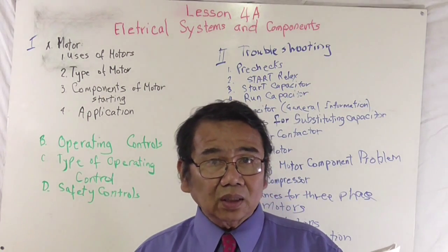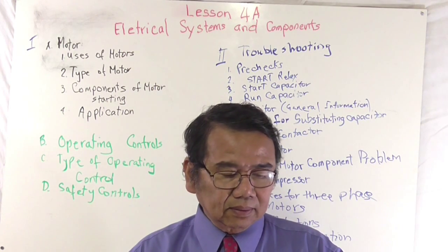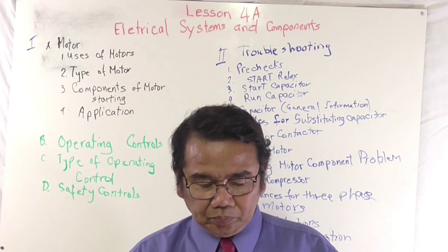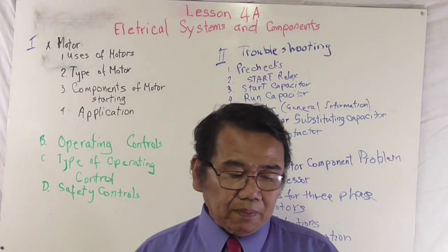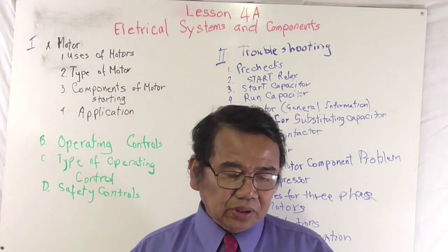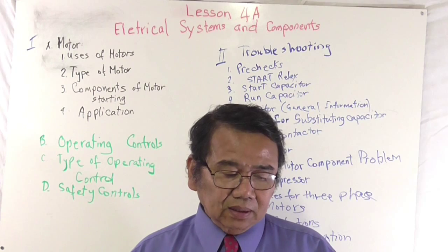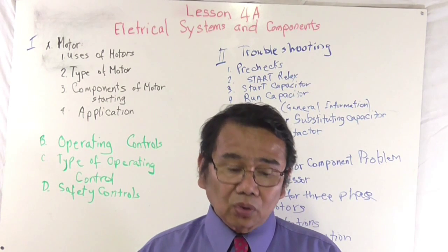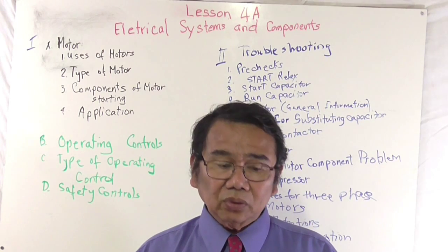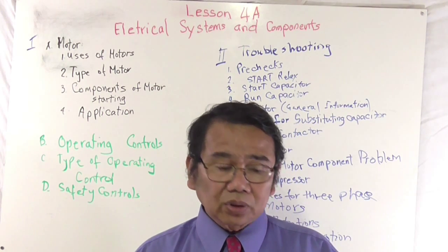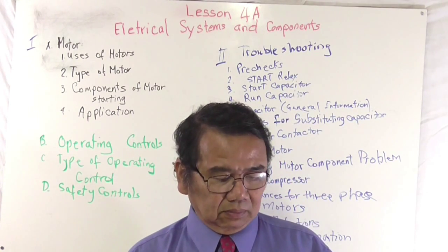Will not close the contacts: relay burned out or wrong one. And then burnout: improper wiring, voltage is low, high head pressure, start capacitor burned out or wrong one, run capacitor burned out or wrong one, low suction pressure, and the compressor burnout.